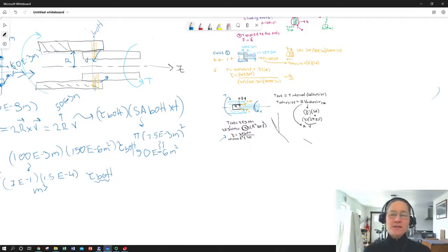So for instance, you were given some kind of project where you had to put two materials together to carry a certain load. You might consider what kind of thickness you needed on those round pipes, if you were looking at some pipes, and how much radius you could use for the interface, and then your material capabilities for your adhesive and for your pipes, and then how much insertion depth you could allow for. The more insertion depth, the heavier the part, because it's doubled up over a larger area.